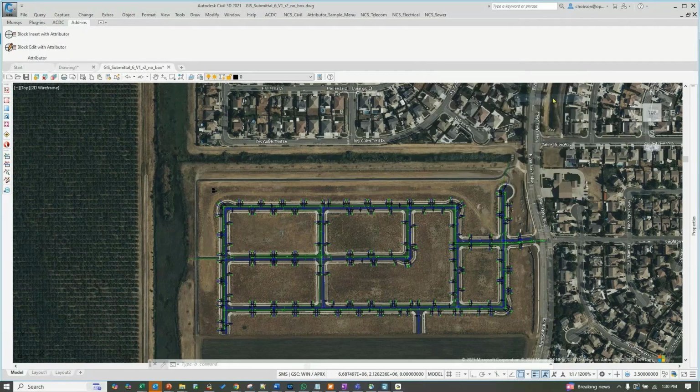And what happens is it is also automatic because of the menu, standard AutoCAD menu, by the way. It's a custom menu, but it's using the same standard tools. And it's basically a macro that says use this layer and use this block name. And so you can see it's already toggled to the right layer. So I didn't have to learn the clean out has to be on that layer. And I can go in.